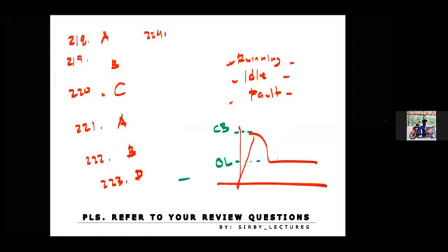Okay, number 224. It is a motor switch. This is a combination of contactor and an overload relay. This is letter C, magnetic motor starter. Number 225. A grain blower is running at 1000 RPM. If the RPM is to be reduced to 700, which of the following is possible for reducing the speed?